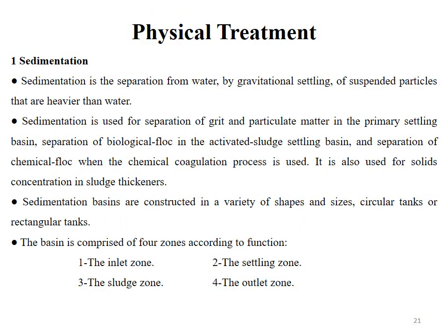And now the physical treatment processes which are involved in wastewater treatment. The first process of physical treatment is sedimentation. It means physical treatment can be carried out through sedimentation. Sedimentation is the separation from water of suspended particles that are heavier than water by gravitational settling.